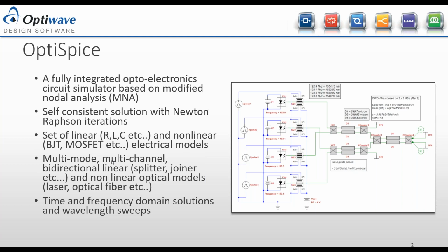Now in our OptiSPICE we extend this concept into optical communications. Normally in SPICE you have your electrical variables, which would be voltage or current, and they're all real numbers. In OptiSPICE we have optical variables that are complex numbers. They're represented either as magnitude and phase or real and imaginary. Optical signals, the way we model them, we get the channel and simulate the envelope of the carrier frequency, and we simulate the phase.